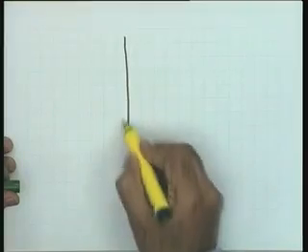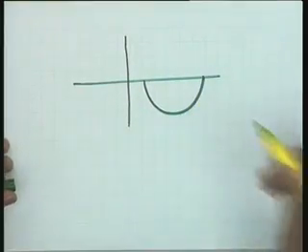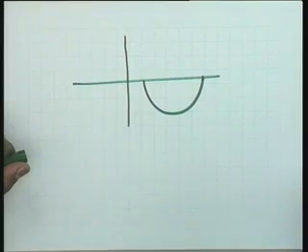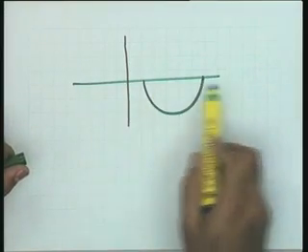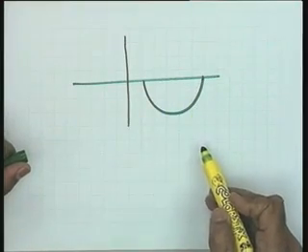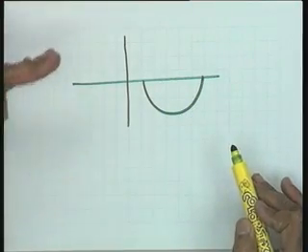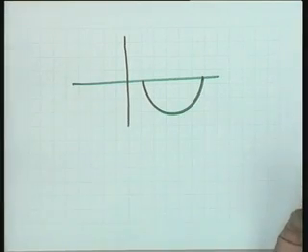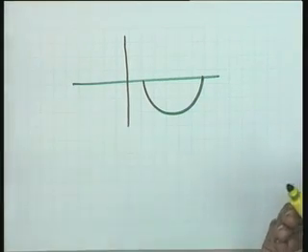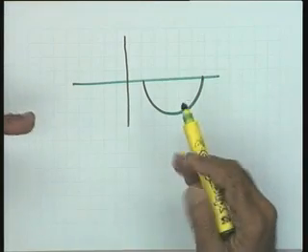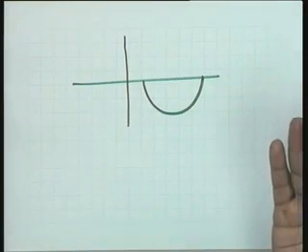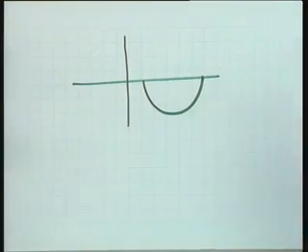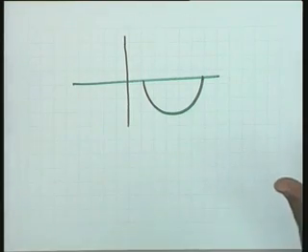Now, I remember there was a question that if the polar plot turns out to be this form, what is the value of the phase margin? How do we interpret the phase margin? There is no direct intersection in this particular case. If you see that you can make an equivalent Bode plot sketch also for this particular system, you will get some value of phase margin more than minus 90 degrees. The statement I had given that time, that this particular system is stable for all values of the system parameters, and therefore relative stability measures carry little importance. That statement is right, there is absolutely no doubt.